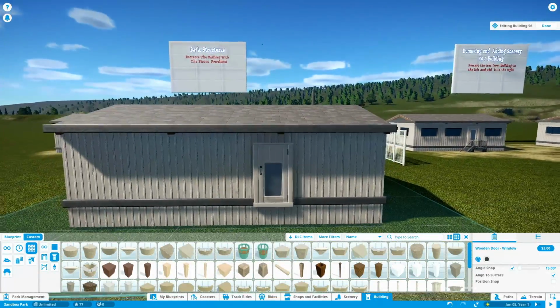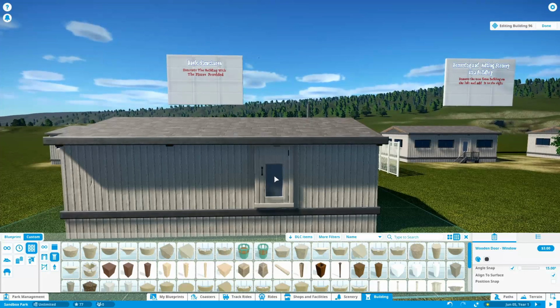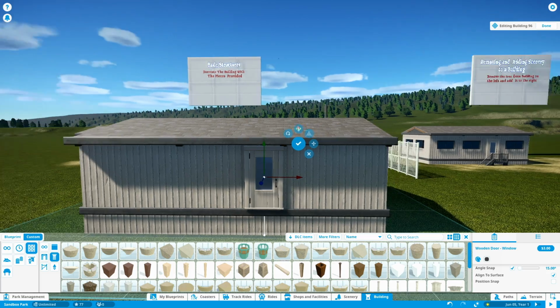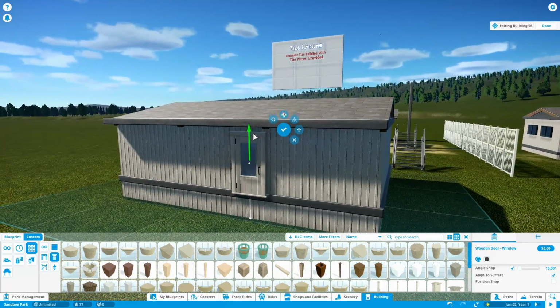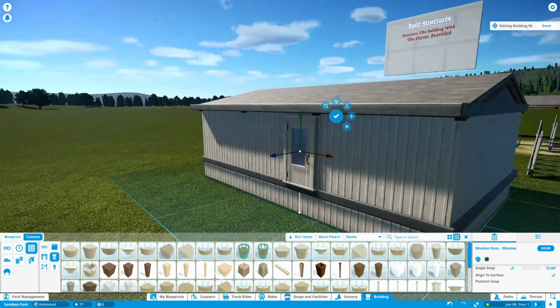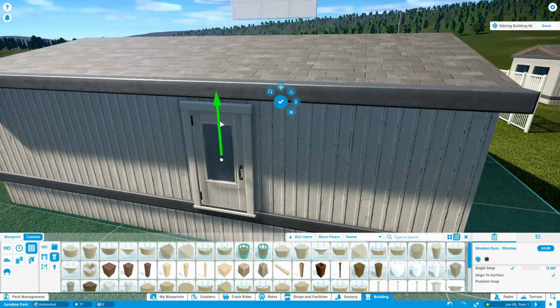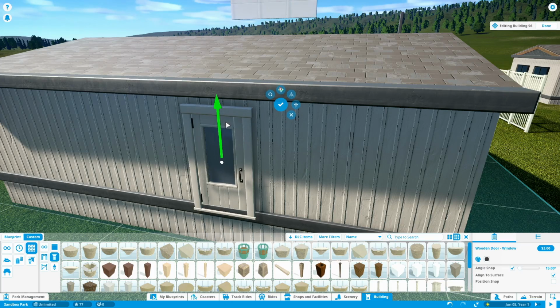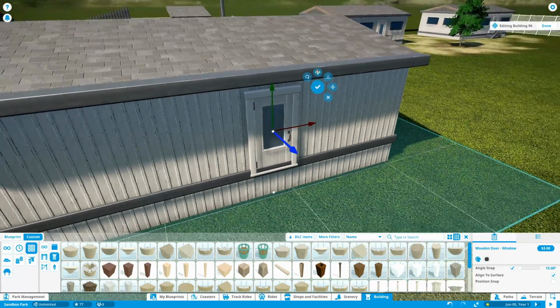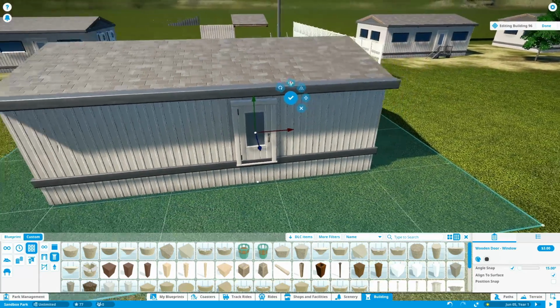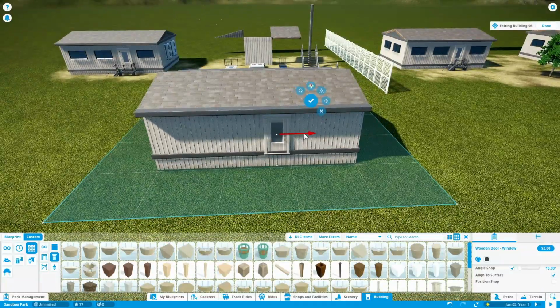And so here's something too. This piece is upside down, so if you hold it on the surface and just hit the Z for rotate, it'll get you to the right direction. And then I'm going to hit X to get the fine tuning in where I want it. Now this door is probably a little bit oversized, so I'm actually going to sink it down just a little bit into that trim, and then we'll hide it with the step.